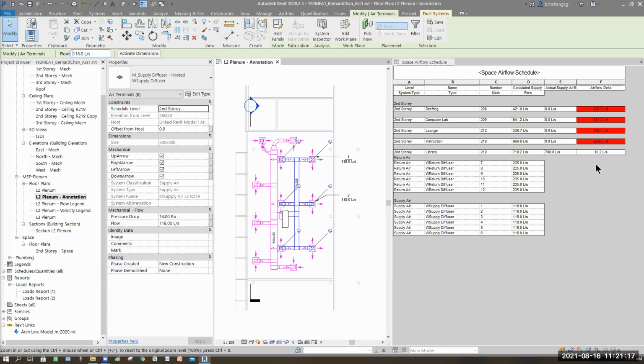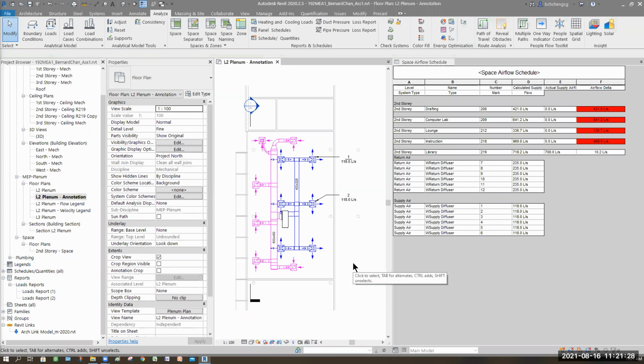You see now? So for a start, we assume that they are the same. We must give them tolerance. Because at the end of the day, if it really goes to the site manager, when this is up, they're going to do testing, right? They're going to run it. Normally, they measure, hopefully it's the same. If not, they have to fine tune the vent inside your air terminal. Open, close, set the valve. Not the valve, right? They actually call it the vent, right? Yeah.